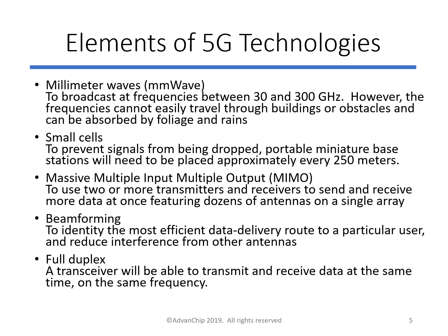Elements of 5G technology. The front runners include millimeter wave, small cells, massive MIMO, full duplex, and beamforming. Millimeter wave. They are called millimeter waves because they vary in length from 1 to 10 millimeters, compared to the radio waves that serve today's smartphones, which measure tens of centimeters in length.